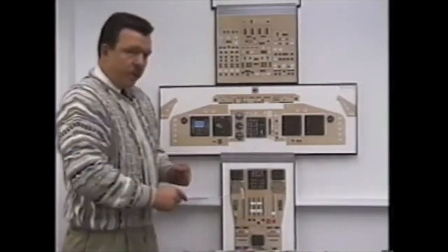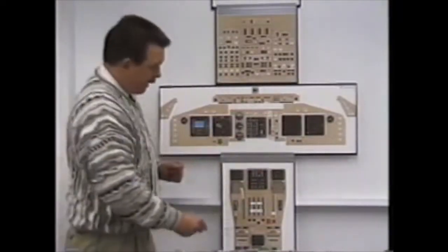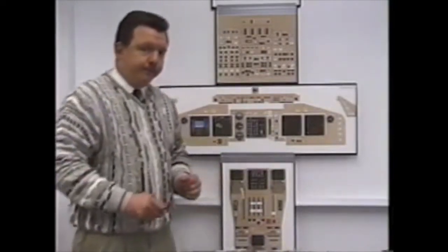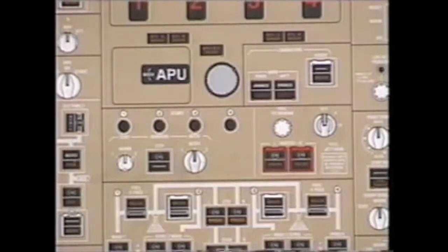If we encounter any one of those problems, electrical or pneumatic power interruption, immediate action for abnormal engine start is fuel lever to cut off and call for the QRC. Starters should disengage at 50% N2. If a starter fails to disengage, the ICAS message will give us a starter cutout message for that starter. The immediate action is to call for the QRC.